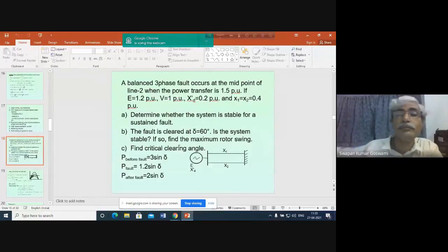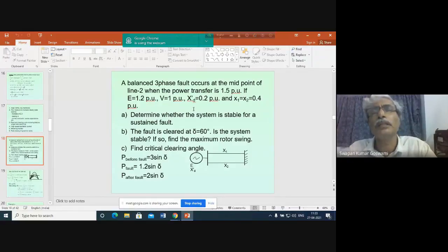Now, during disturbances, what happens? During disturbance, say a fault occurs. When a fault occurs, what happens? Say a fault occurs at the terminal of the generator. Then, since the terminal voltage becomes zero, obviously there will be a large current. So a large disturbance occurs, a fault occurs, and the generator is delivering large current. So now the question is, what will be the reactance of the generator under this condition? Will it be same as the reactance offered by the generator during